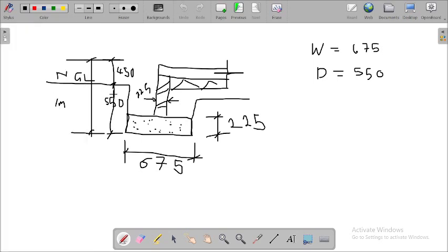So that being said, this line you have here, like a U, that is housing the foundation concrete, is our excavation line. It's our excavation depth rather. If you check from this point to this point is the width of your concrete. That means that the concrete is taking the entire width of your excavation. So the width of the concrete is equal to the width of excavation. Therefore, we said W, being the width of our concrete, is also the width of excavation, 675.